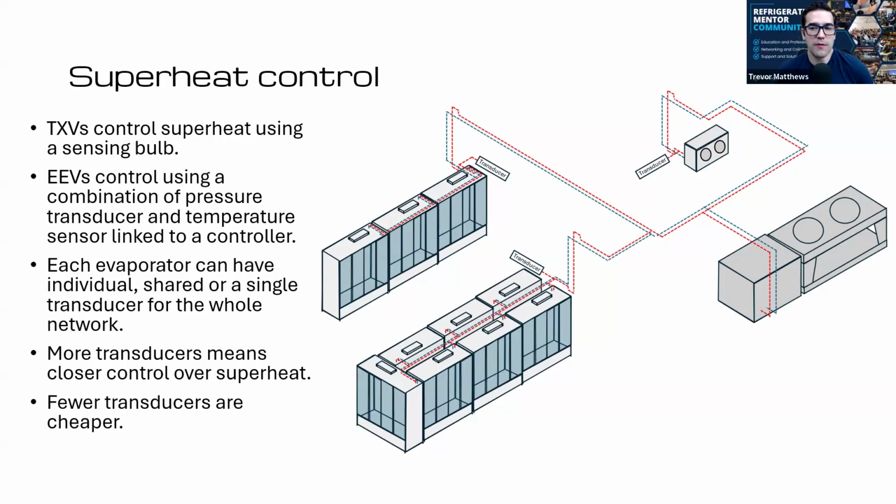For me, I've always had every coil have a transducer, because now I know what that specific valve is doing, like the EEV, as well as that coil. Now with a transducer serving, for example, those 7 cases, as long as it's piped properly and you don't run into any issues, those valves will work great. But what happens if you have one transducer but you have 2 frozen up coils? How does that affect all the other cases now with one transducer?